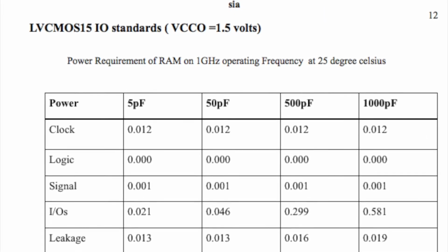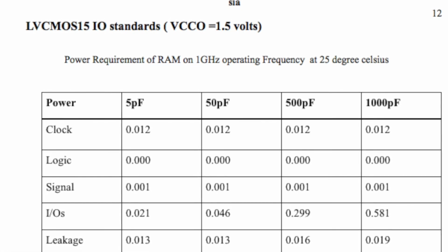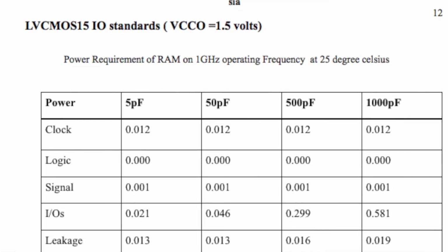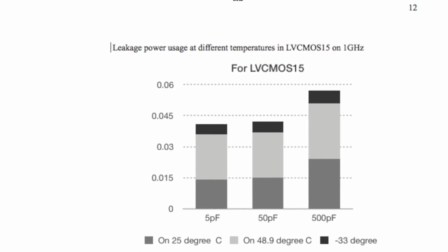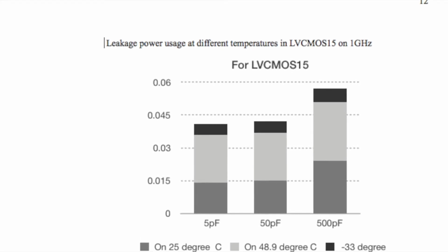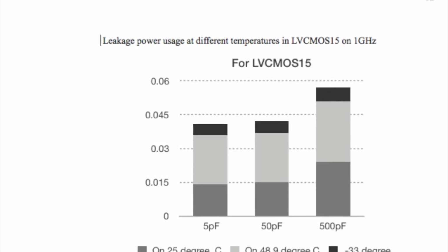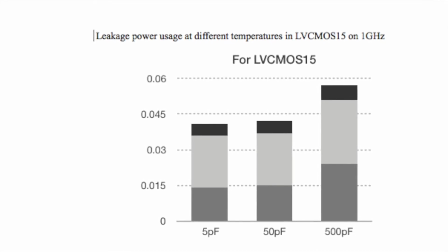The leakage power increases as the capacitance value increases. Therefore, to get lower power consumption, the capacitance value should be low. Also testing at different peak temperatures, the graph shows that the lower the capacitance value, the lower the leakage power. In different temperature scenarios, the leakage power at the hottest temperature is still lower than that observed at the coldest temperature.